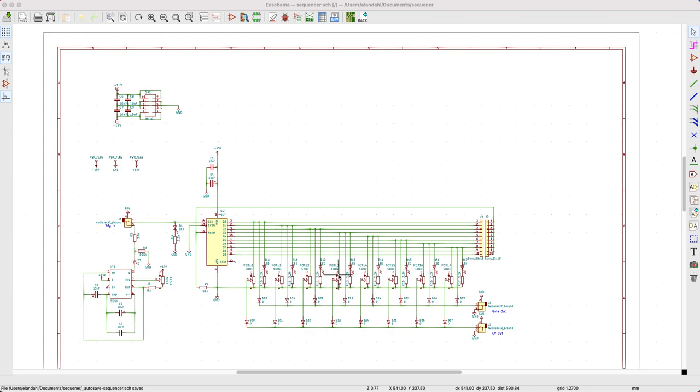You don't want the voltage produced, say, by channel 3 here to run back into, say, channel 2 and affect things. Therefore, a diode is added to each output. The net result of this CV out is exactly what we saw on the breadboard version. The voltmeter was reading the voltage series that came out, and this is what we were sending in to the VCO to make different tones.